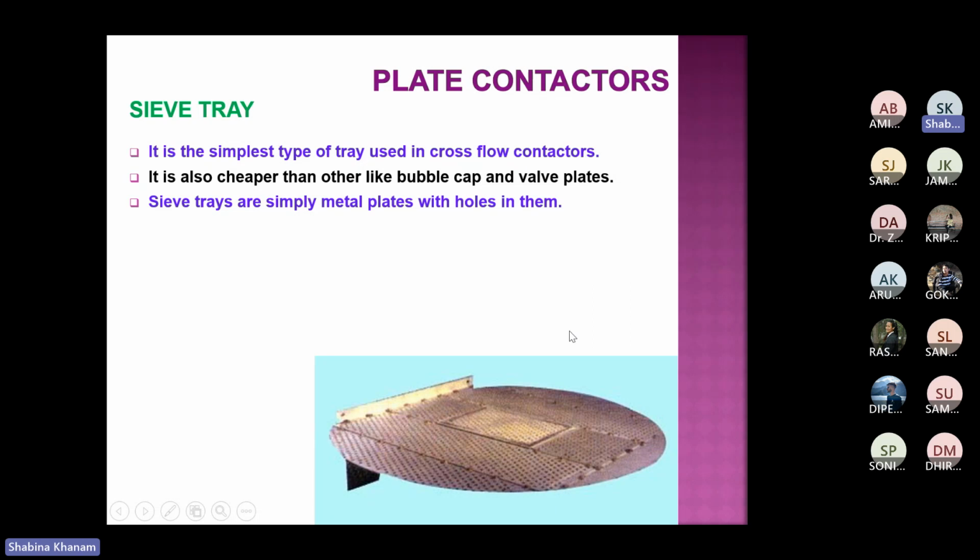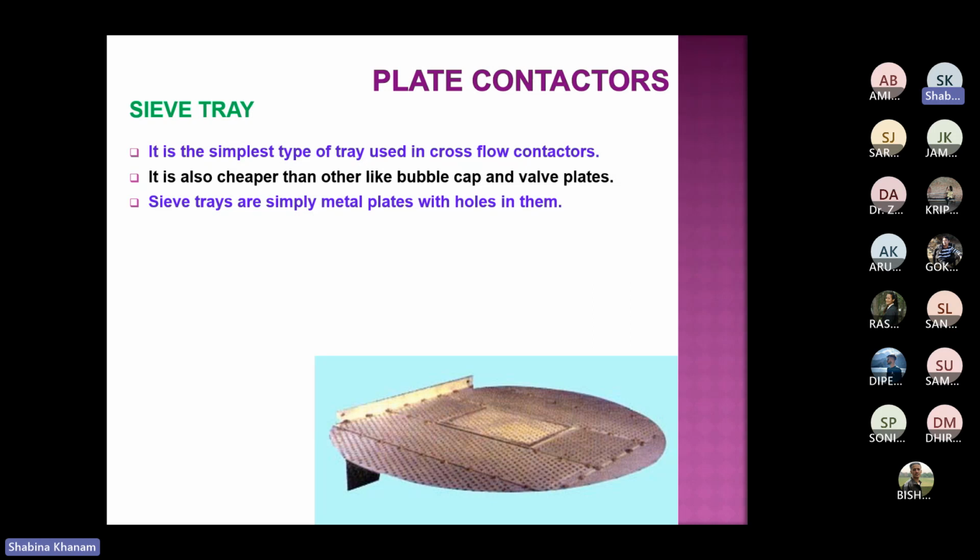The reason being, if I ask you how the plate is attached to the distillation column, how can you imagine that attachment? Because these are already attached at the inner periphery, right? So how are these plates attached? If you consider this particular section where the plate is available, we consider a metal ring of this shape only.